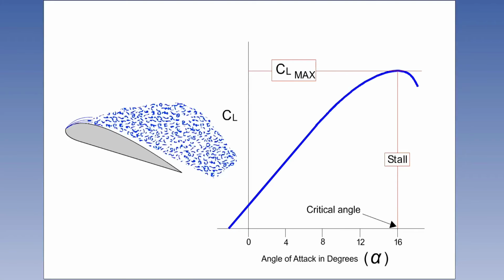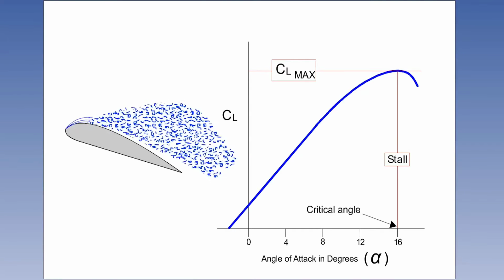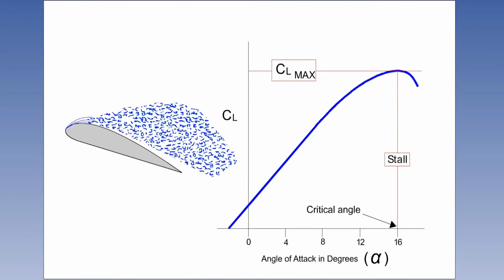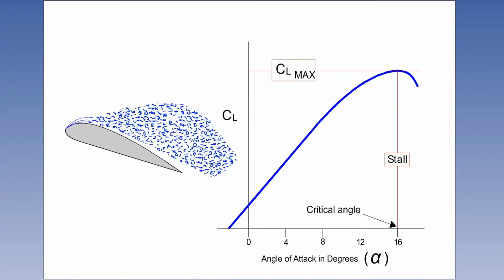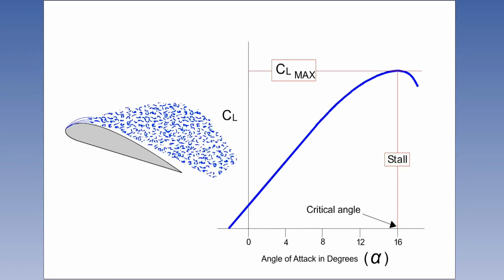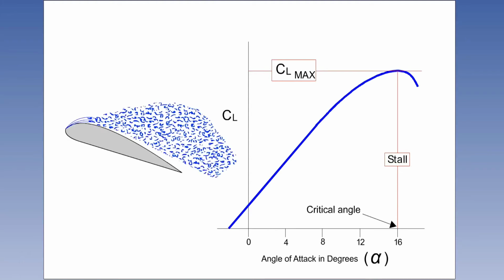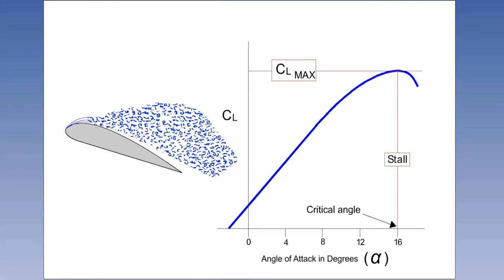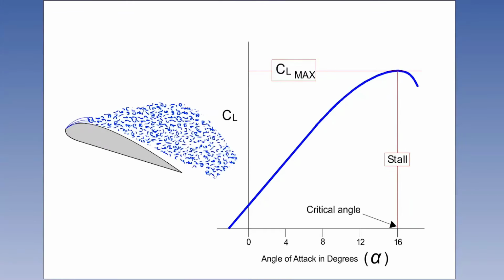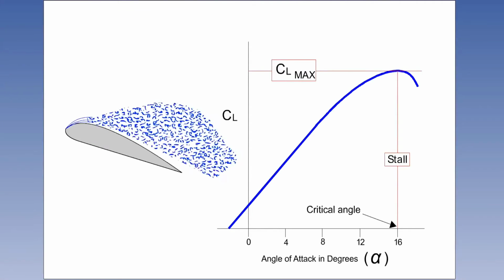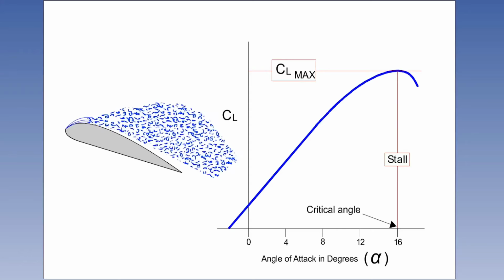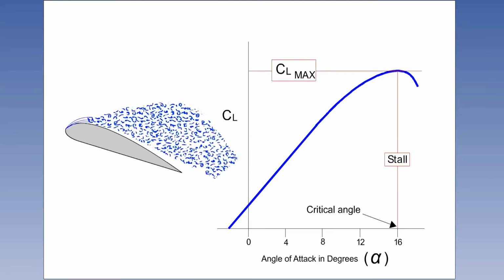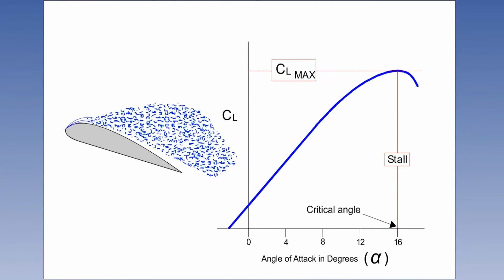If we study the lift curve shown in this sequence, it can be seen that the increase in CL is linear over a large proportion of the range of alpha up to the stall. But as the effects of separation begin to be felt, the curve begins to flatten. Eventually, CL reaches a peak and then drops at an angle steeper than the rate of increase. The alpha at which it reaches its peak is called the critical or stalling angle of attack, and the corresponding value of lift coefficient is CL max. Most aeroplanes will stall at around 14 to 16 degrees alpha.